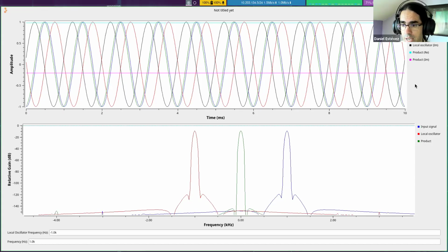It might be receiving an RF frequency which is pretty high. The last session we were playing with signals around 100 megahertz, which were broadband FM radio stations. But the thing is, the ADC, the analog to digital converter, which is inside the radio, works only at a few megasamples per second. So that means that to digitize those radio frequency signals, first we need to convert them to much lower frequencies, essentially to move the signals of interest pretty close to zero so that we can sample them and convert them to digital values. That's how mostly every radio receiver works.